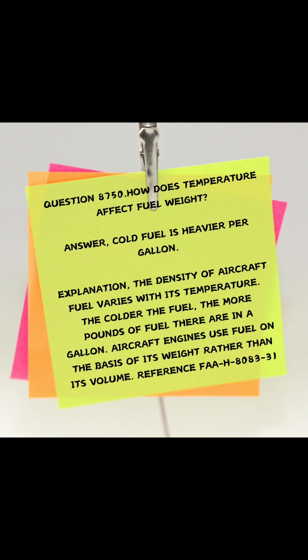8083-31. Question 8750. How does temperature affect fuel weight? Answer: cold fuel is heavier per gallon. Explanation: the density of aircraft fuel varies with its temperature. The colder the fuel, the more pounds of fuel there are in a gallon. Aircraft engines use fuel on the basis of its weight rather than its volume. Reference: FAA H